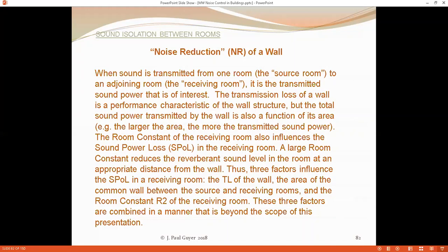And sometimes the ductwork is lined on the inside with sound absorbing fiberglass bats, and that absorbs quite a bit of the sound from the fan room, and then the potential is reduced for sound to move from one occupied space to another occupied space.